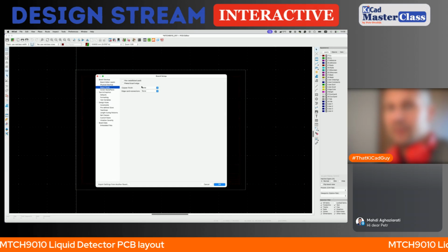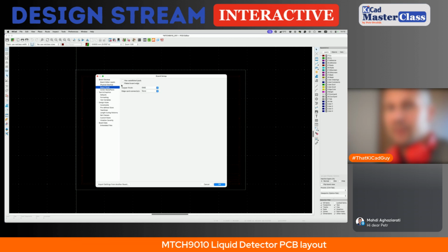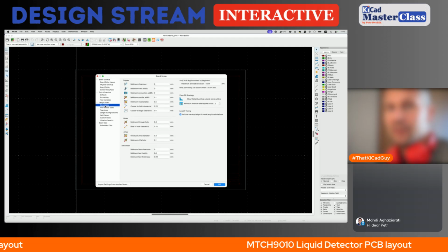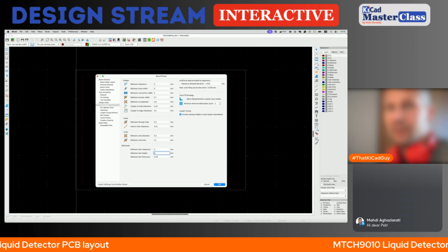Sorry. Board finish will be ENIG, but just for the sake of the render. Solder mask expansion 0.07. Constraints. I think just the minimum text height will be changed to 0.7.